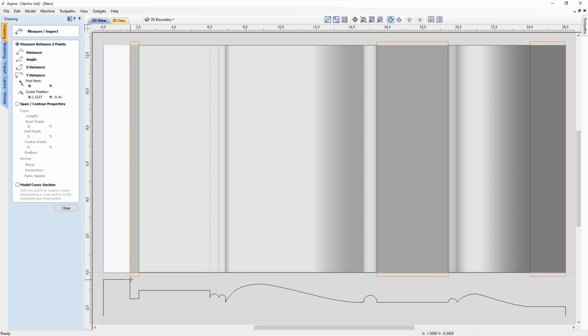We're going to measure from this point here. We know that that is the top surface of our spindle, so that's at the very edge of our spindle. So we're going to click there. Then we're just going to go down, and then we're just going to click here. We can see the distance there is 1.075. And so knowing that this point here is equal to the outside of my cylinder, we can actually use this measurement to create our pocket depth. So at 1.075, we're just going to make a note of that, and that's the depth of cut for this